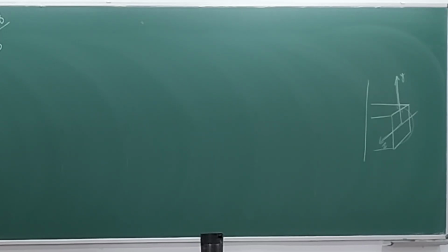Basically you have to find such a pressure which will ensure that the stresses developed in the wall of the pressure vessel will not exceed that weld strength.